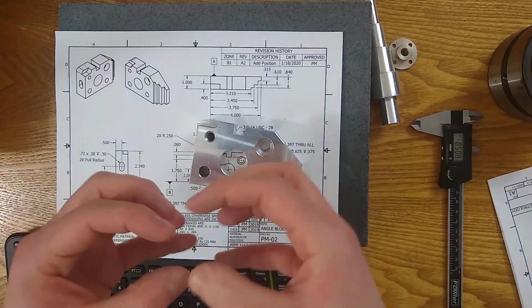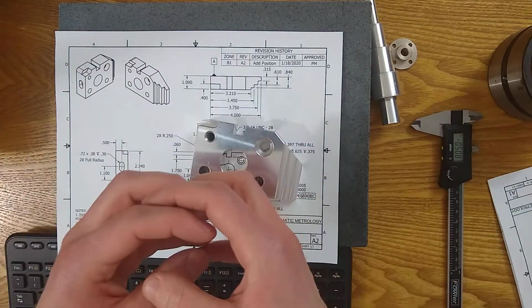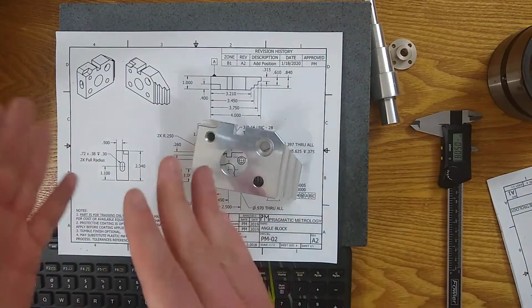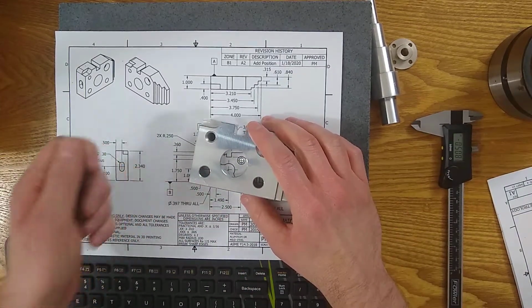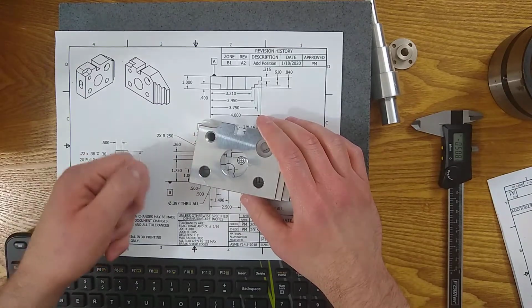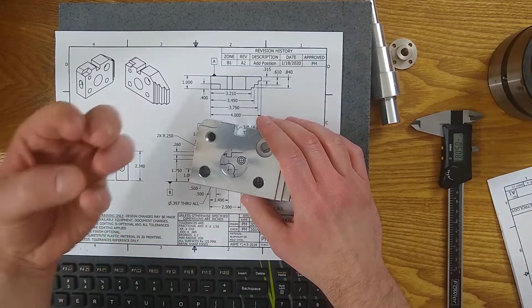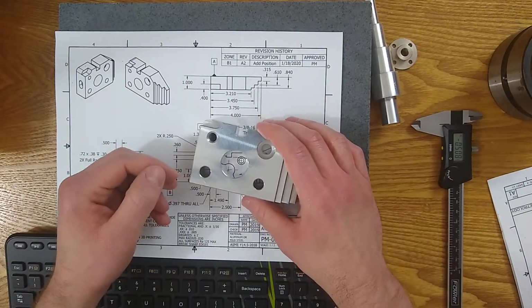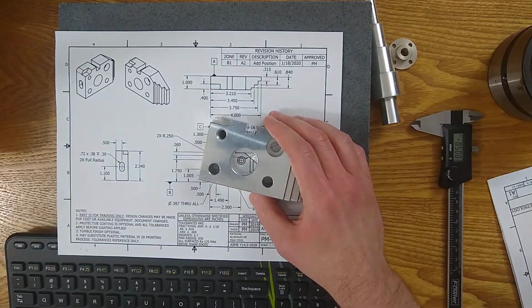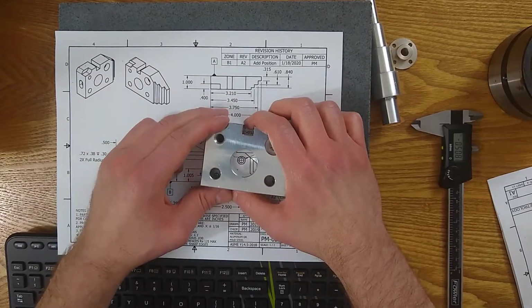If all of these things are working correctly, the go, no-go gauge will work. If one of them's off, usually there's an issue with the go, no-go. So those go, no-go plug gauges will check a lot of this all at once. That's why only the thread diameter, pitch, and class are called out, none of the other details that went into making the thread.